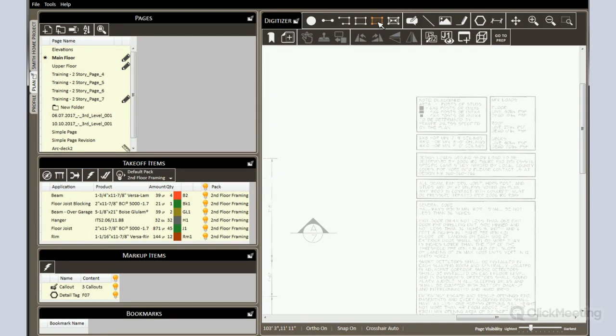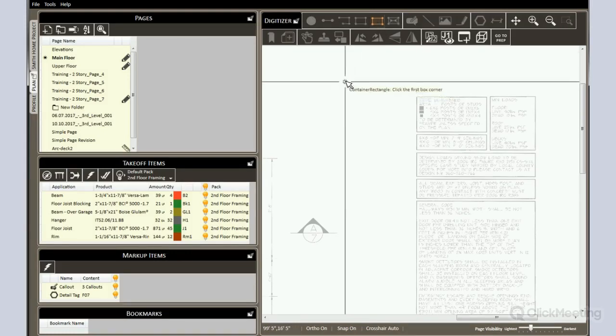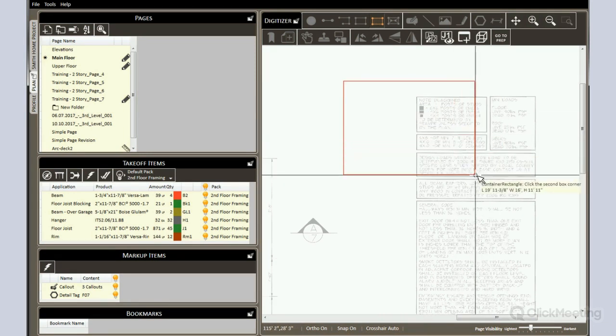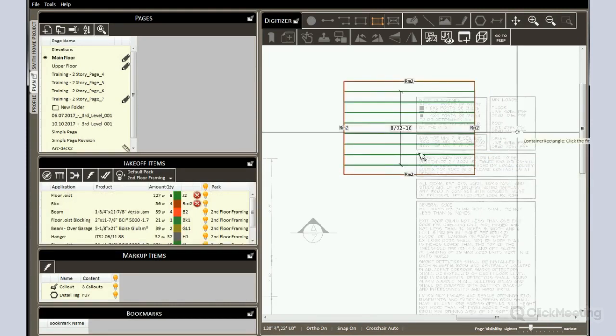But if you hold down the shift key while you start the tool, and you look at the tooltip, you'll be in the container rectangle mode. In this case, you can just click one corner of the container and drag, drawing a rectangle or a square, and click the other corner of the container. And then by 2 clicks, you've actually put your floor container in. So for maybe more straightforward areas, just like little box areas, you can draw that more quickly.